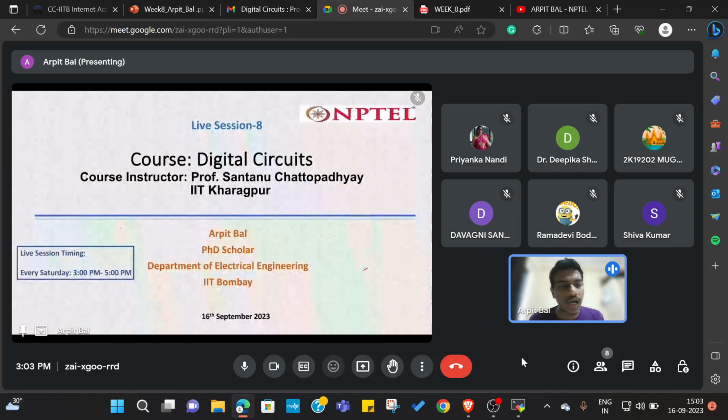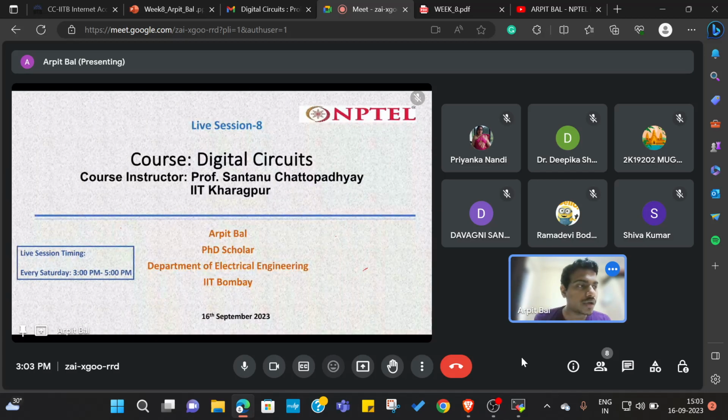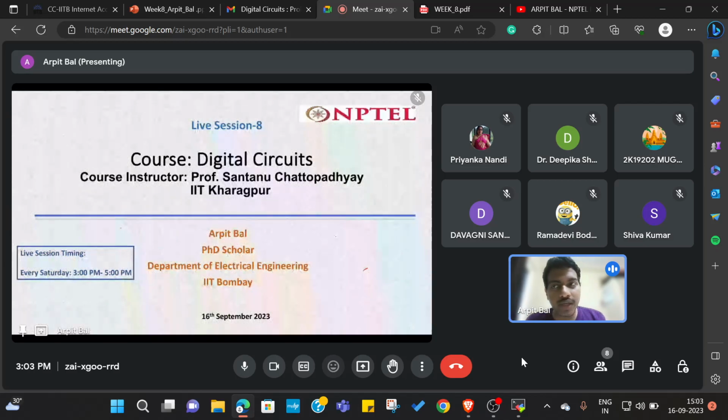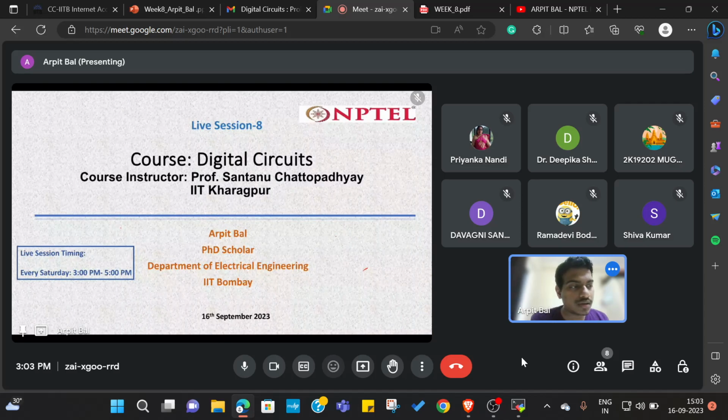Before starting today's live session, I would like to summarize a few things related to Mealy machine and Moore machine. We have one question related to that in today's session, and then I'll also give you a brief summary about DAC and types of DAC that have been covered in the lecture, and ADC. Okay, so starting with Mealy machine and Moore machine. Mealy machine is something in which the output is a function of present state and present input, whereas Moore machine is something in which the output is a function of the present state only, right?